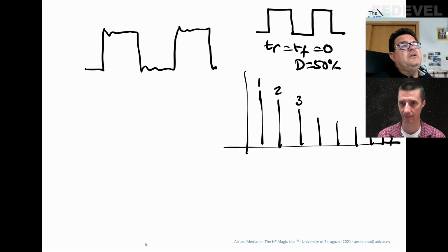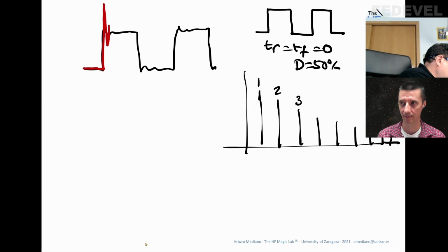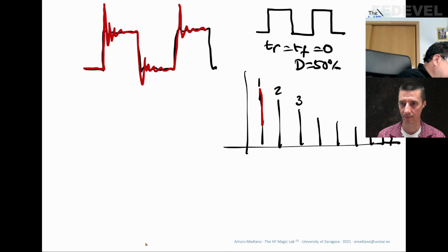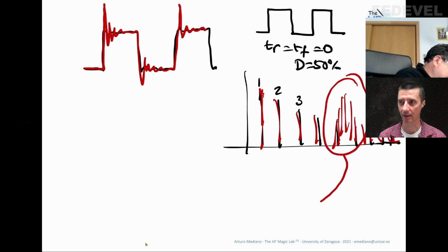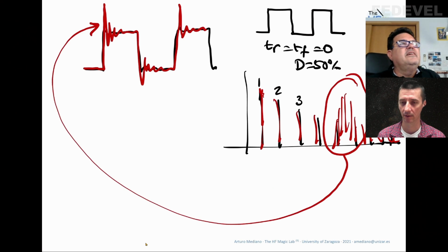In our signals, you don't usually have this, so you find the second, the fourth, the sixth harmonic, no? But if you have something like this in your circuit, which is very common in electronics, what you can find is something like this. You can find the different harmonics, and at some specific frequency, you can find the peak. No? Because of the other frequencies which are in the ringing. Exactly. The ringing in the signal is introducing energy at some specific frequencies.